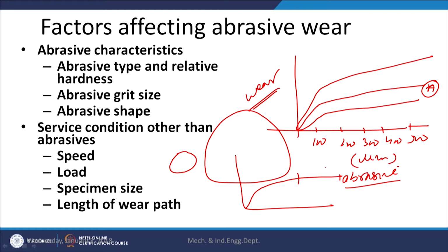So, beyond a certain size, a further increase in the size of the abrasive will lead to the situation where, under the given surface conditions, the abrasive may start getting fractured, and the size will start getting reduced. So, an increase in abrasive size increases the wear up to a certain critical level. Thereafter, there may not be a significant increase in the wear with the increase of the abrasive size.